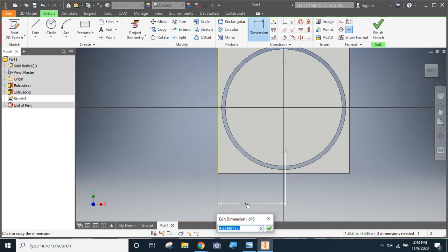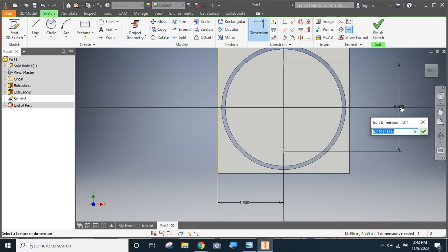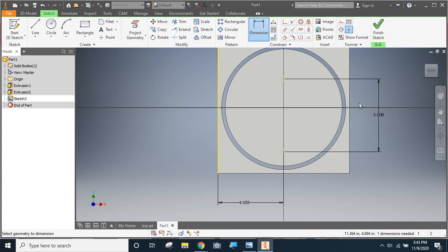I want these points to be centered on my project. So remember that board underneath was 9 inches. So I'm going to do this 4.5 inches over from the edge. Right, because I already constrained the top and the bottom to be aligned. When it moves this bottom one, right, that top point moves with it as well. And now I'm going to take and dimension these vertically. So the first thing I'm going to do is click my 2 points. I'll drag my cursor over here and click to open that dialog box. I want a 5-inch space in between these 2 points. So I'll type the number 5 and hit enter.